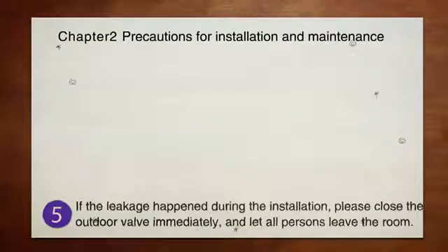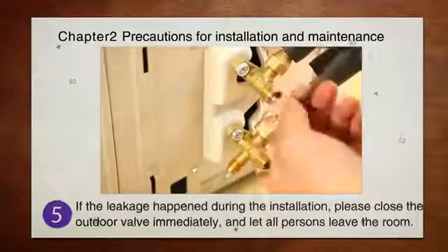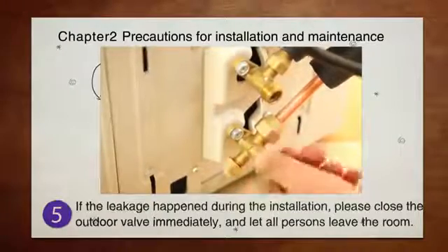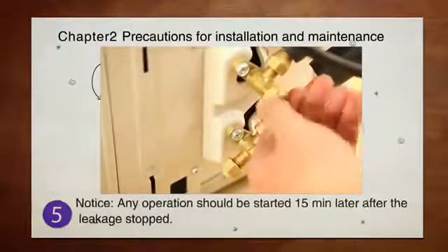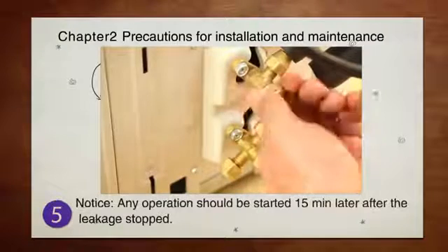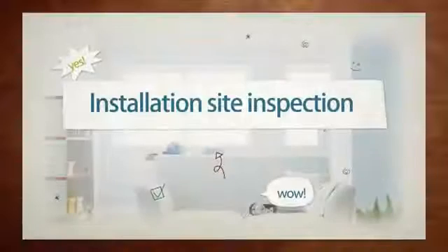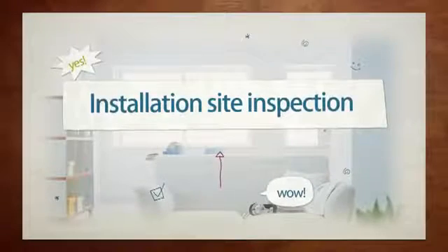Number 5. If leakage happens during installation, please close the outdoor valve immediately and let all persons leave the room. Notice, any operation should be started 15 minutes after the leakage stopped. Chapter 3. Installation site inspection.